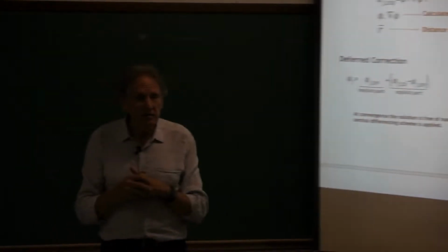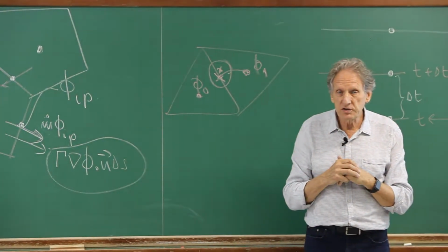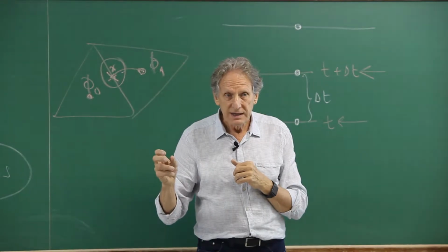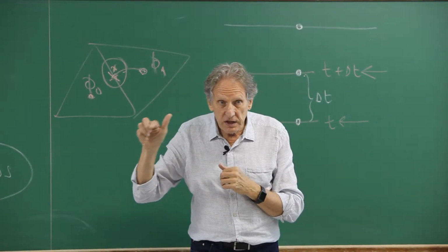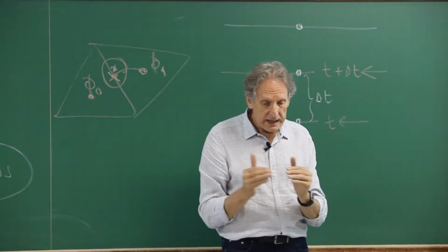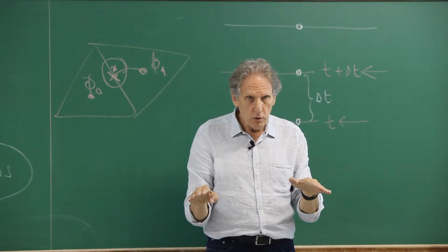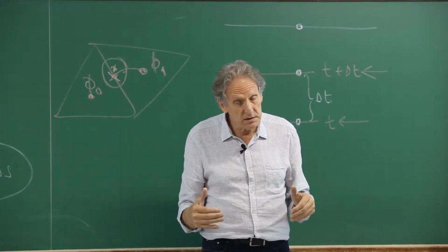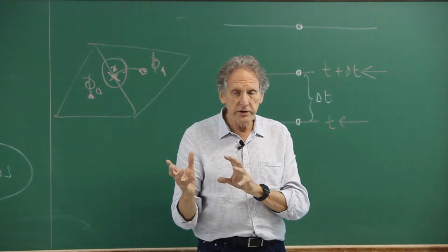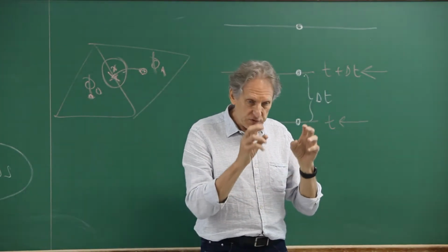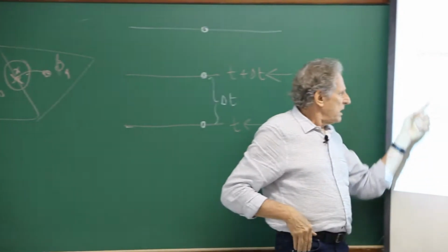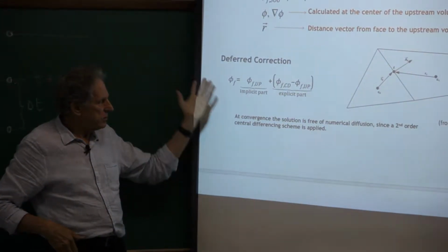And we are going to see central differential scheme does not produce numerical diffusion. Central differential scheme produces numerical oscillation and not numerical diffusion. So this algorithm ends up with no numerical diffusion, but it may be prone to some numerical oscillations, which is another error which comes from the approximation of the advection terms. You know? Well, it's written here what I just said.